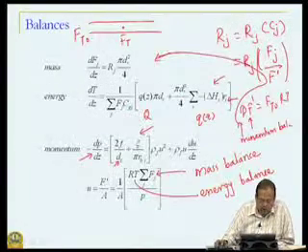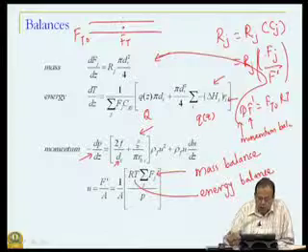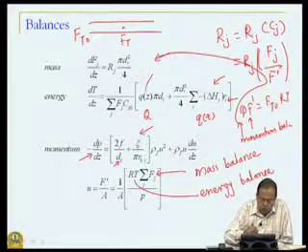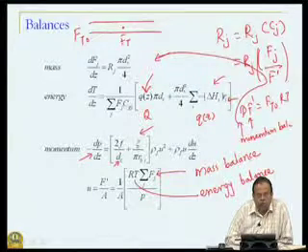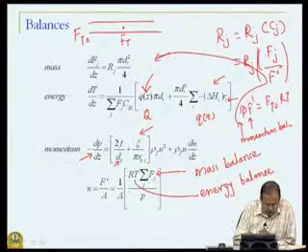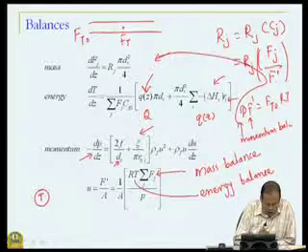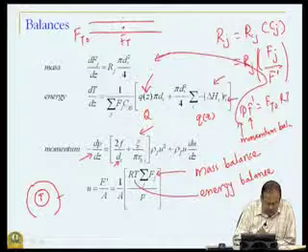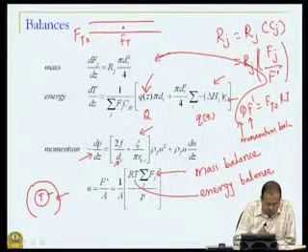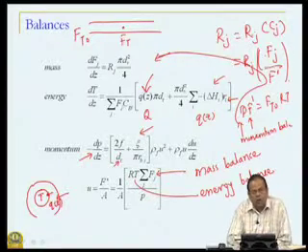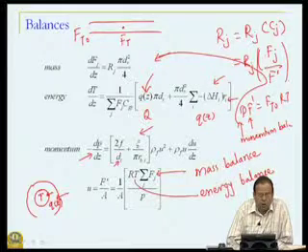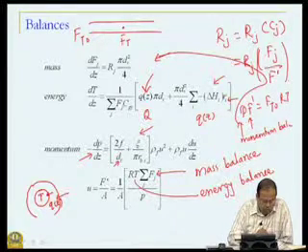Now, I mentioned that in this model we just assume that we are going to program our furnace to achieve these heat flux balances. Suppose this is my tube in which ethane is flowing and this is my shell, and I am just saying that there is going to be some heat transfer from here to here, which is Q of Z. If I want to make this model more realistic, why do I bother about Q of Z?